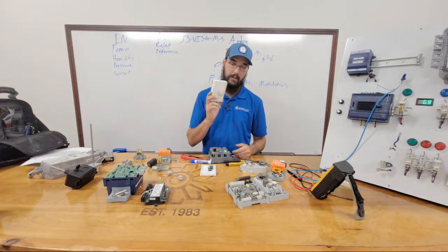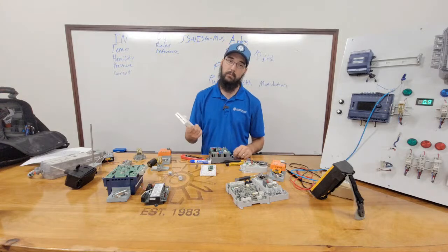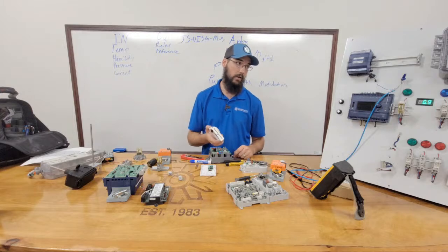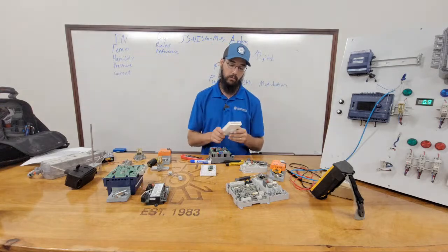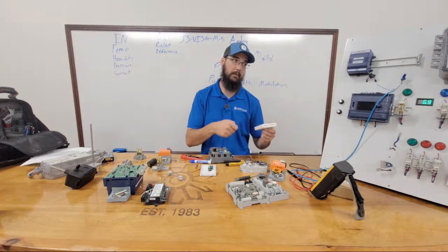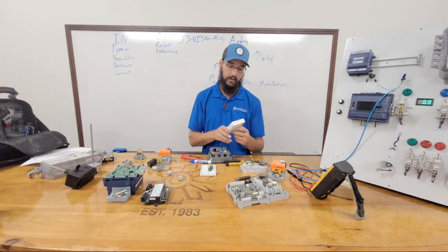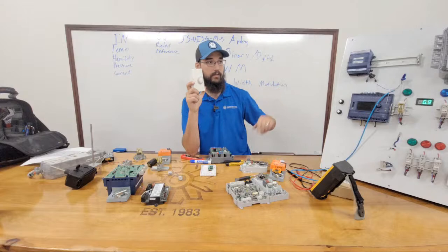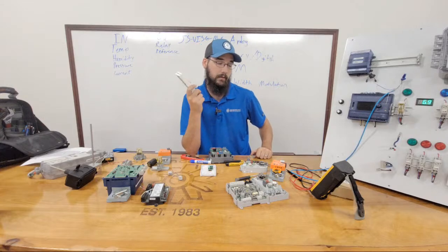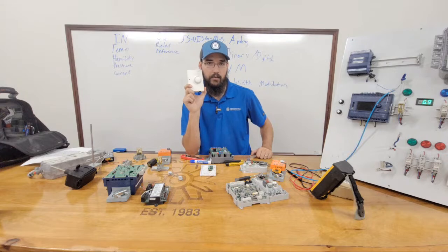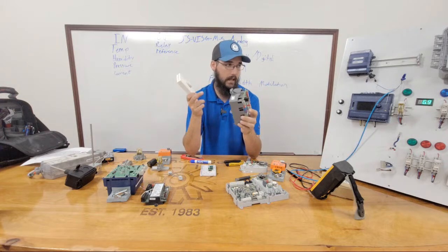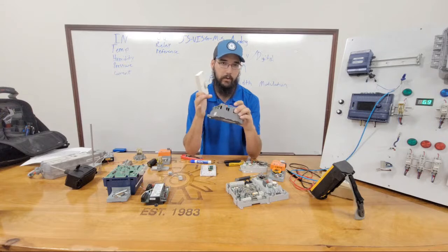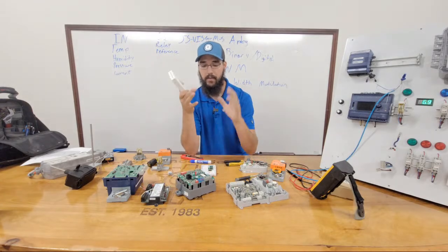So the easiest solution I could recommend is either the customer have one, you have one, or go take one that you do find is accurate, pull it off the wall, unplug it, take it to where you want it, plug it back in, and then see, does the other module that you already verified was working across the room, or maybe across the office, do the exact same thing. So if they both read identical, then it's likely a logic issue or could be a cable. If the cable's got a weak point or some kind of resistance being generated in it, that can give a false reading.